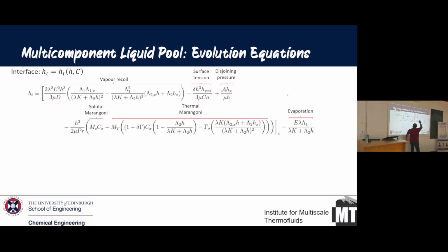Of course, one of the things is surface tension. This is a crucial role. And there is another term which I've put here, the disjoining pressure. And there is a reason for that. Now, whenever you have a very thin film, I've just exaggerated this, and you've got this height of the interface which looks like that. It is forming these waves, and sometimes the height of the interface almost goes very close to the wall.